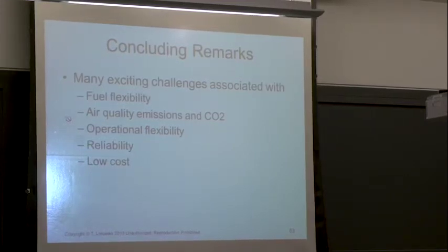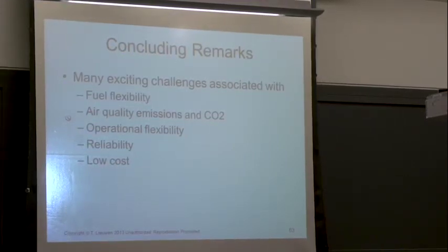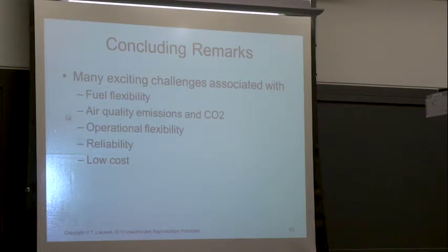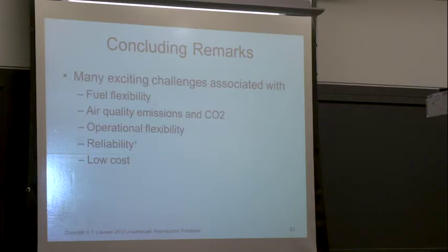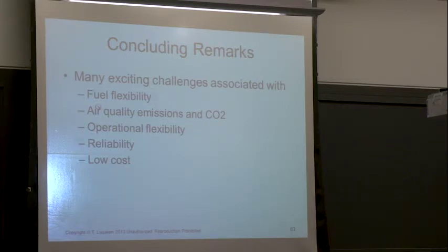But let me just wrap up this last section, which is that there are lots of really interesting challenges associated with steady flowing combustion systems around fuel flexibility. I've talked a little bit about that, but as you look at future fuels, renewable hydrocarbons, synthetic hydrocarbons, biofuels, things like that, you have to balance air quality emissions and CO2. I gave you that example. I talked a little bit about how we're now at the point where if we want to go to higher efficiency cycles, in other words, lower CO2, we're going to have to rethink NOx.